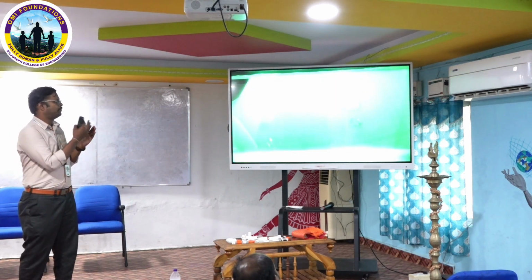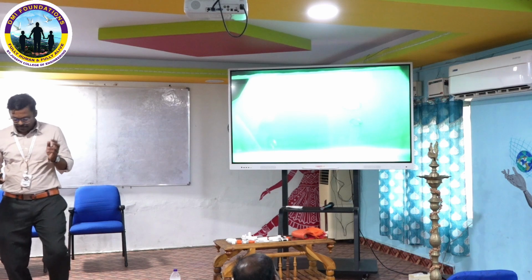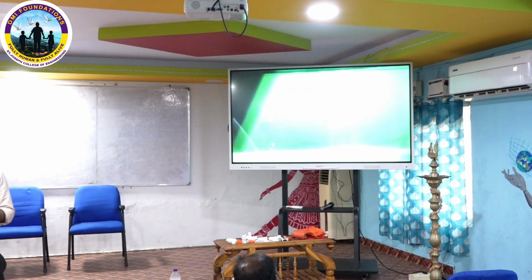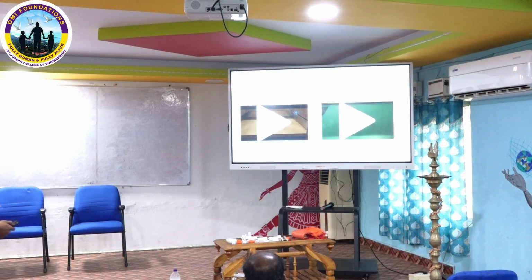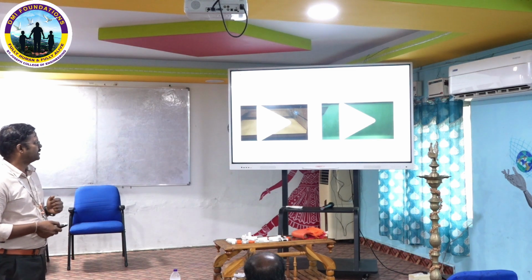With these applications, what is important about the powder bed fusion process is that the unsintered powder acts as a support for the polymer-based additive manufacturing, which is called SLS. In DMLS we need to give support structures. Even though we need to give support structures, to fabricate more complex structures compared to SLA and FDM technologies, we can get more complex parts, which we have shown already. So this is the laser powder bed fusion process.